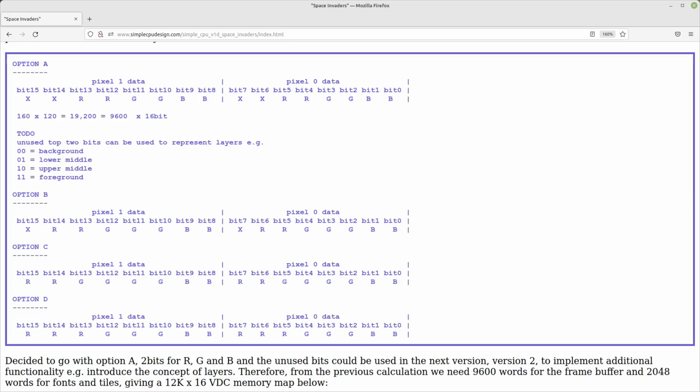The reason for that was I was trying to preempt any memory clock speed issues when dealing with the control logic that would be writing this data to the display. So rather than implementing it as byte memory, implementing it as 16-bit memory meant that you could effectively prefetch pixels, so that in one memory transaction you were reading 2 pixels worth of data, increasing our memory's bandwidth, and as I say, hopefully reducing the required clock speeds.